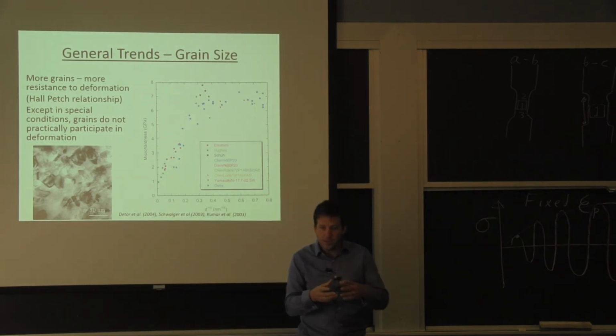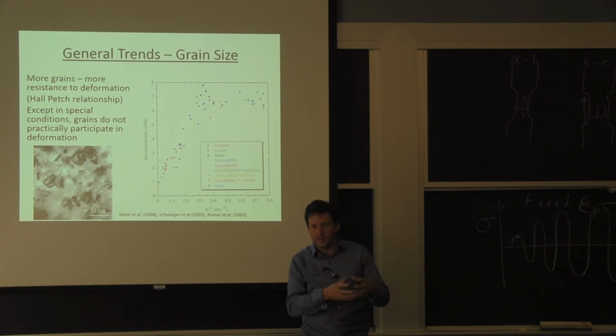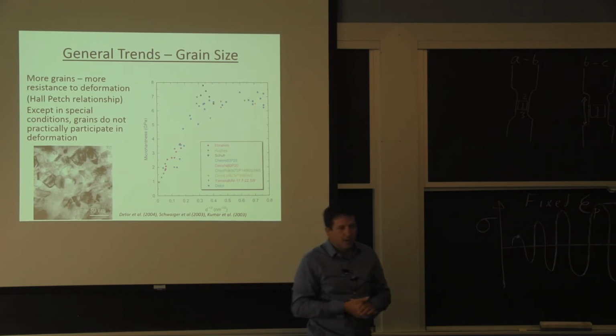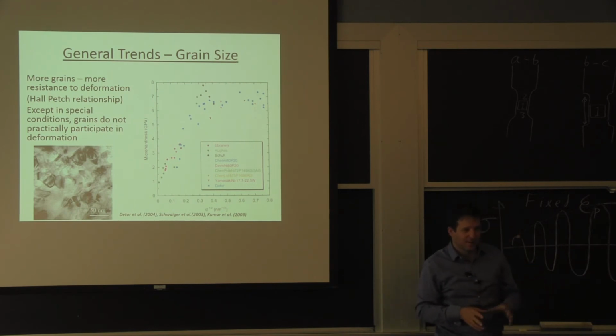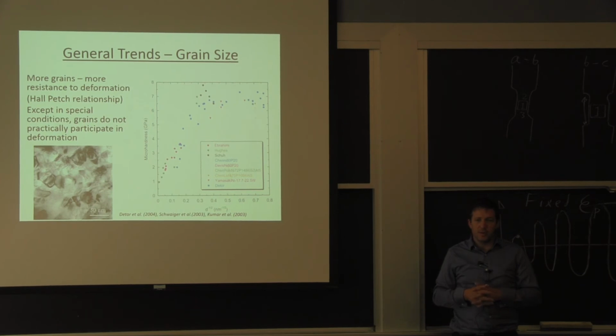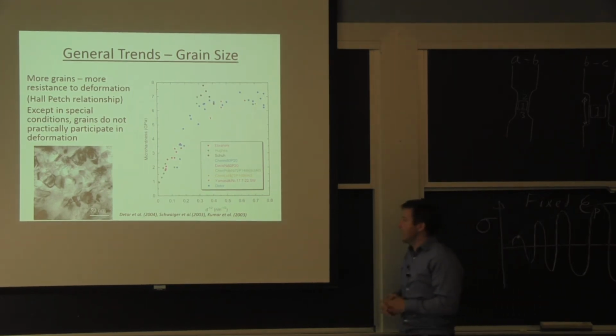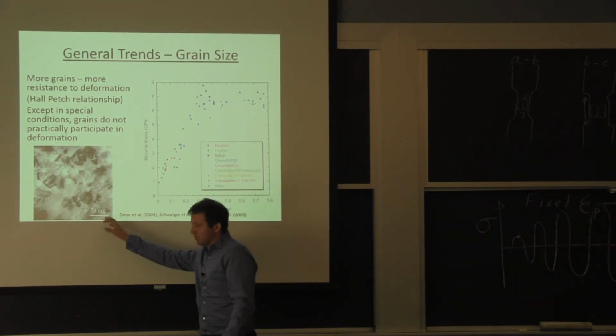When the dislocation reaches the grain boundary, and it's really small, it's possible sometimes for the dislocation to get in the grain boundary. But there is a lot of energy there, and a lot of times it will just stay in its own grain. So don't think of, oh, the dislocation is going to go from one side to the other of the piece. That's never going to happen. It's confined to its own grain, and it could go to the grain boundary. It happens more when you have very, very fine microstructure.